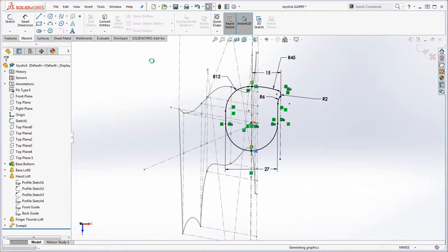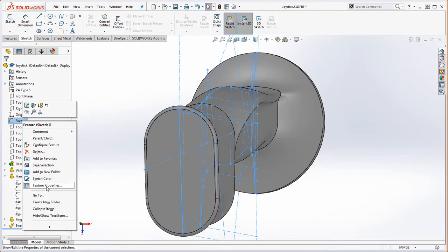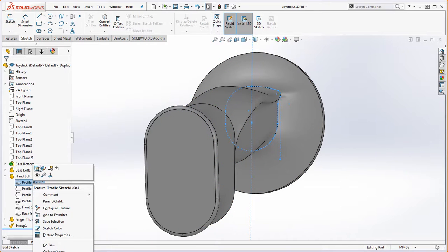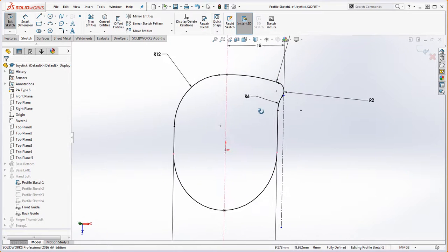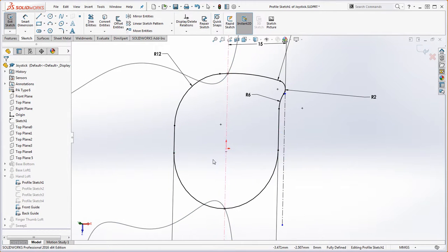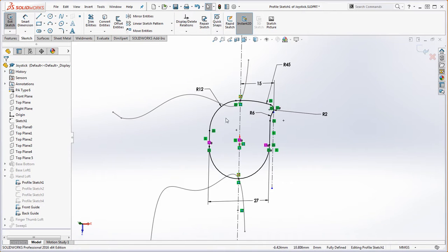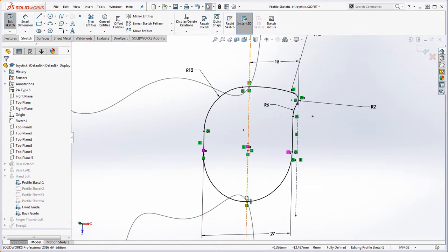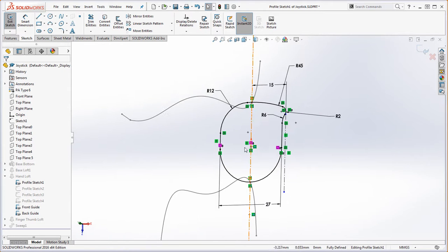So let's actually just rebuild that, and we're going to take that design sketch. Remember to relabel that. Points off if you don't. We're going to go ahead and hide that. For every one of these profiles, when we go into them, you want to take your front and back guide too, and we want to see that. You want to make a relationship with the guide curves. It's just a whole lot simpler because there's no other distracting geometry out there that you can select. But here you can. So you want to make sure each one of these pierce relationships are on that.